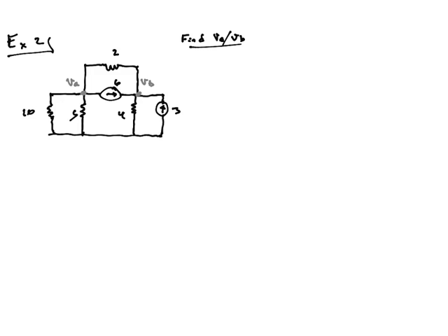First step, choose a ground. Okay, here's my ground. All of this stuff down here is the ground. Next, nodes. Well, obviously A and B, because I want to find the voltage at A and the voltage at B. So that's easy. Now what we want, currents.